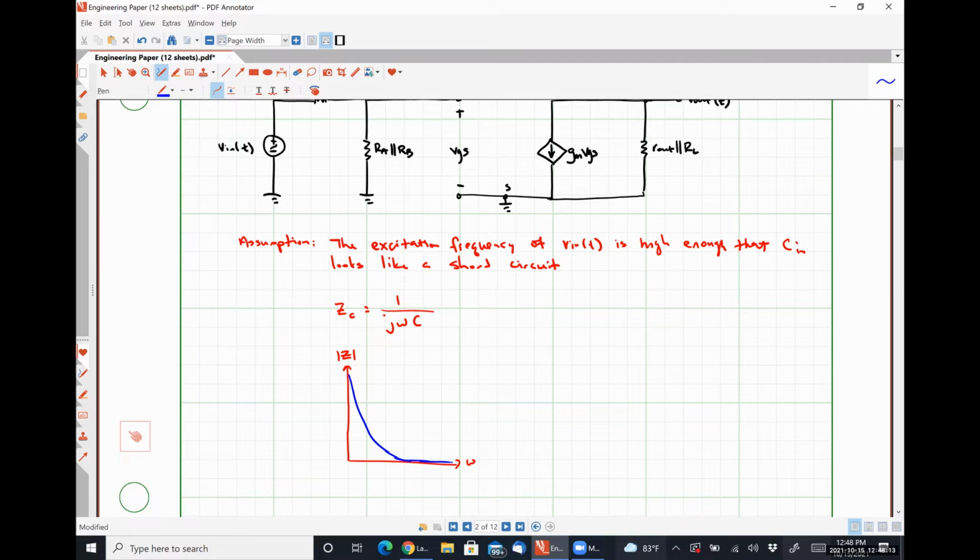If we were using this as a design choice, we would need to make sure to choose our capacitor value in such a way that it behaves as a short circuit at our frequency of interest, right? So typically speaking, that input capacitor is going to be a large capacitor, right? But we can tailor how large it needs to be based on our application.